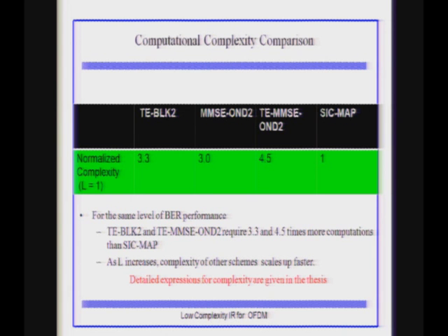So this is for one iteration. That's right. Now let's answer the questions that you posed. One is, when silicon is so cheap, why do you care about all these multiplications? Not always. And there are two scenarios. One is mobile applications. Say, for example, an 802.11 receiver or transmitter, when you have both transmitter and receiver in a laptop or a mobile phone. I know in our group we are doing all sorts of gimmicks to bring down the power consumption. The silicon area and the cost may not be all that much of an issue, but when you have bigger silicon, you need to power it up always.